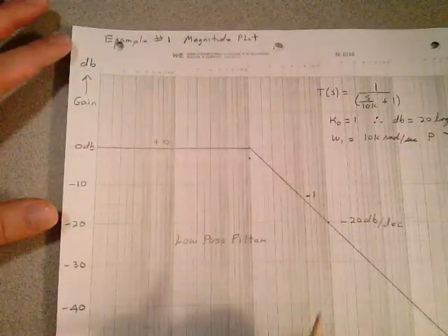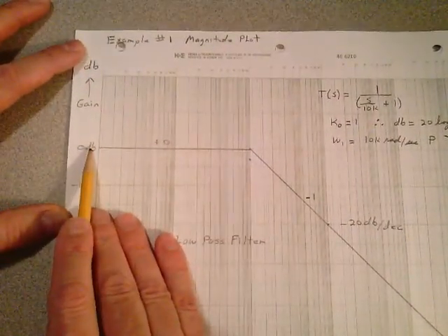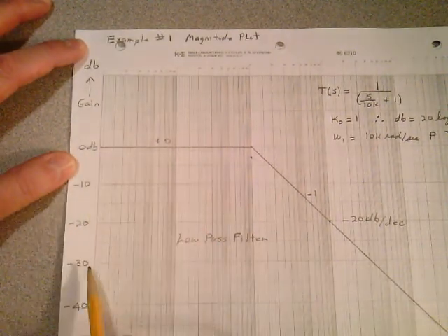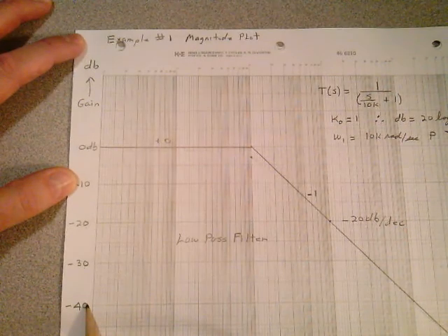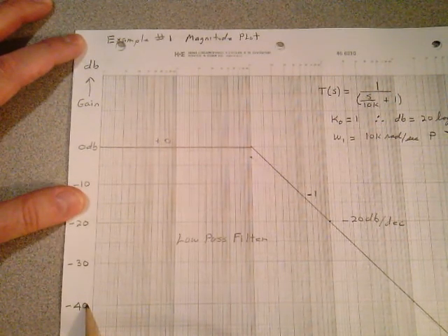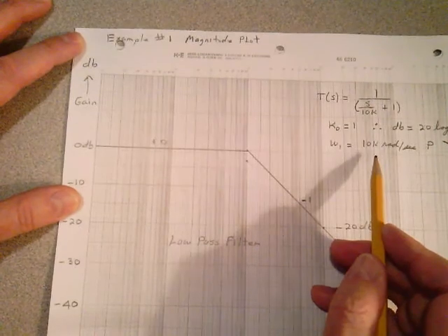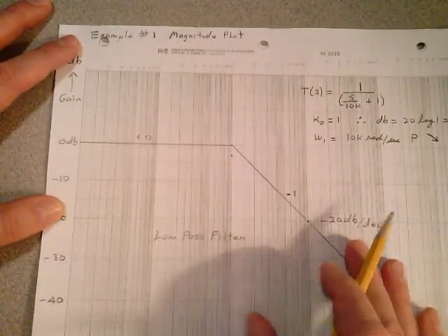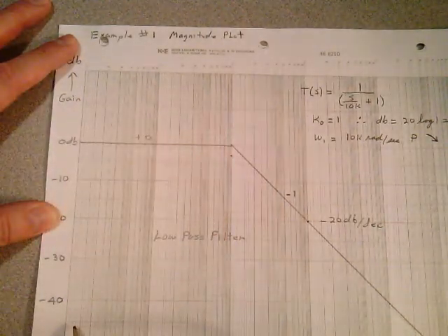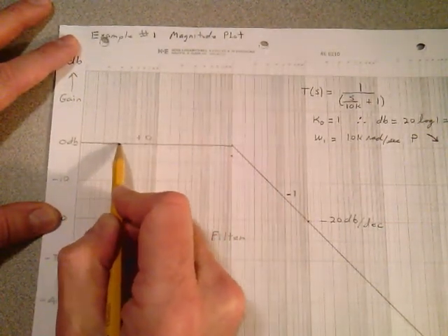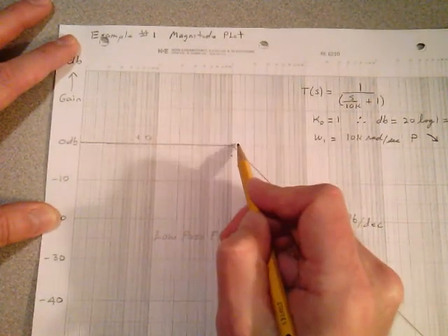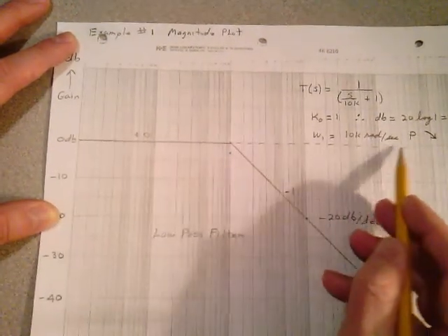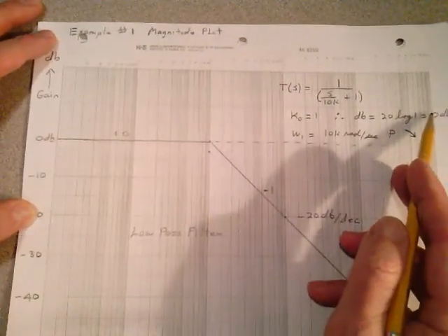So what I decided to do is put my 0 dB up here, and every inch was 10 dB. So if that's 0 dB, I put a minus 10, a minus 20, a minus 30, and a minus 40. So the contribution from the K0 term, if you look at it, is 0 dB. So you take your log paper and you label your vertical axis, and you notice the 0 dB is the contribution from the K0 term. So you just dash a line the whole way out here, showing you your contribution from your K0 term, which was 0 dB up here.